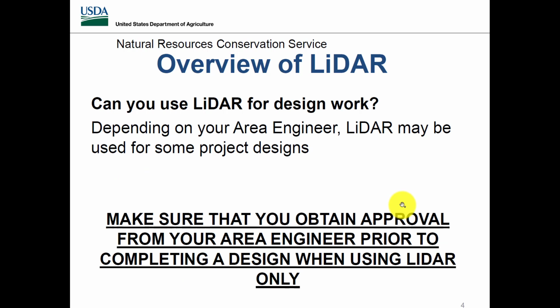Can you use LiDAR for design work? Depending on your area engineer, LiDAR may be used for some project designs. Make sure that you obtain approval from your area engineer prior to completing a design when using LiDAR only.